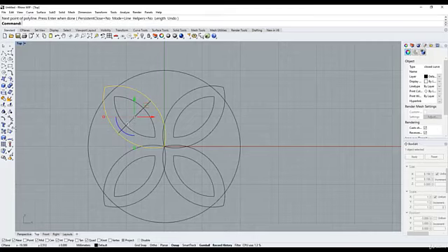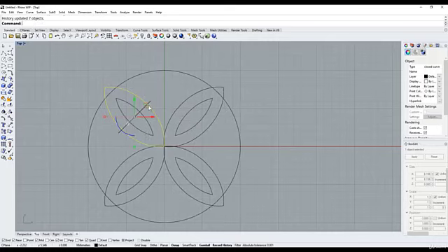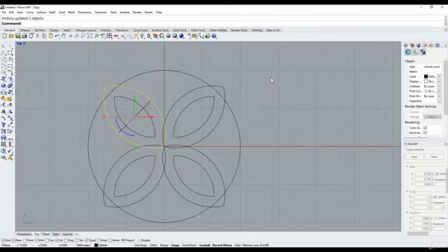And I'm going to come down to transform. And I'm sure we've got a scale button here somewhere. Ah, there it is, scale 3D and 2D. If I cascade that out, I'm sure we can scale 1D. So in this instance, I prefer to just type scale 1D rather than have all of these cascading menus, but you'll see that the effect is the same. So the base point here, I want to come to the middle of this line that we made, come out to the edge, and then I can just scale that in and scale that out as I like.